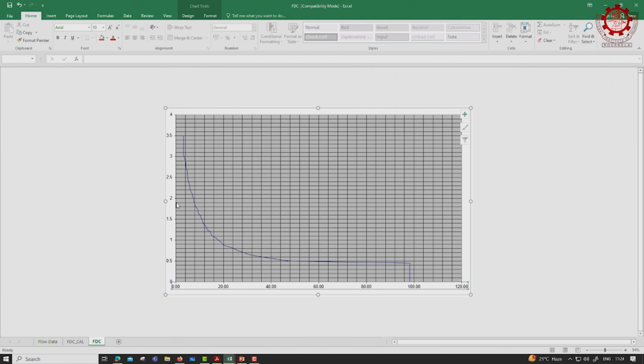And if you put, say, 2 cubic meters per second as your rated flow, I will put these numbers here. If I select 2 cubic meters per second, my plant capacity will be very high, because P is equal to Q rho G H, so the rated capacity will be much higher. But you can run only approximately 8% of the year; each side is 4%, 4, 8, 12, 16, 20.